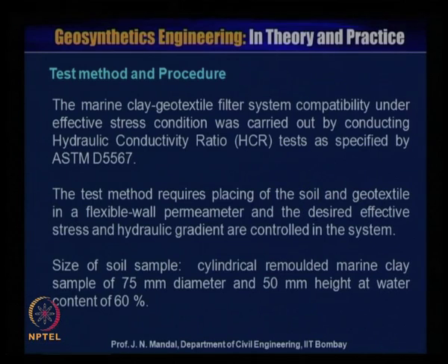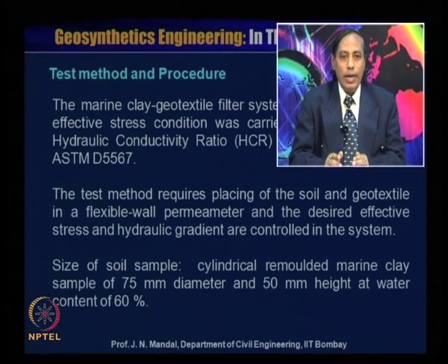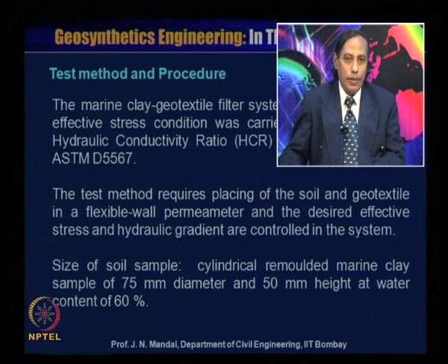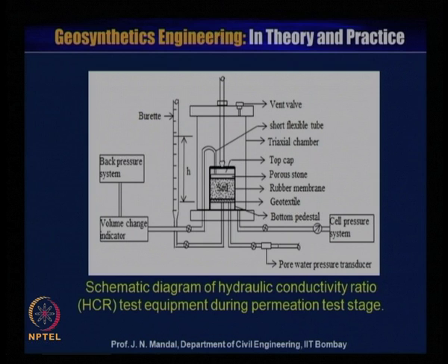The test method requires placing of the soil and the geotextile in a flexible wall permeameter, and the desired effective stress and the hydraulic gradients are controlled in the system. Size of the sample: it will be a cylindrical molded marine clay sample of 75 millimeter diameter and 50 millimeter height at water content of 60%. Now, here you can see